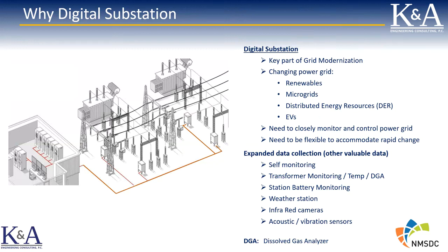We're also working with the utility on a major program designated the sensor deployment program, where again, they're expanding their data collection capabilities by installing things such as transformer monitoring systems for oil temperatures and winding temperatures, dissolved gas analyzers, station battery monitoring, a weather station, infrared cameras looking at transformers for temperature signatures, and also acoustic and vibration sensors.